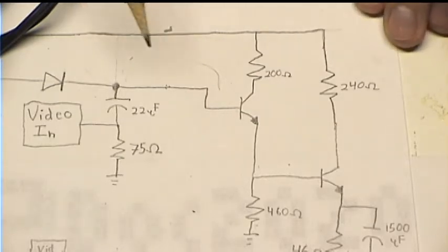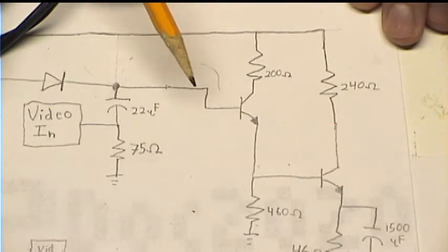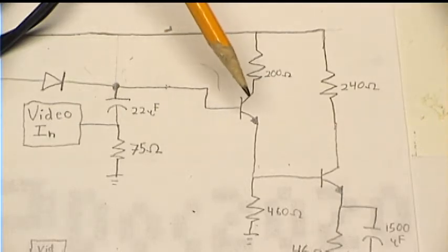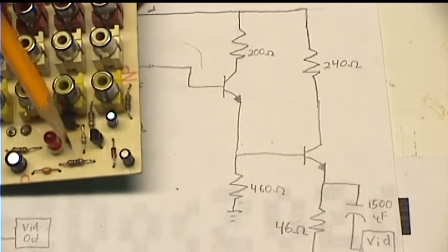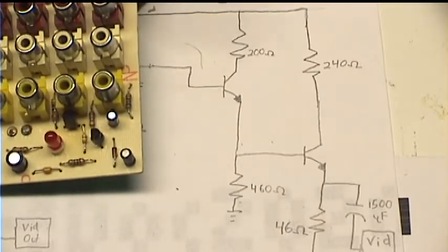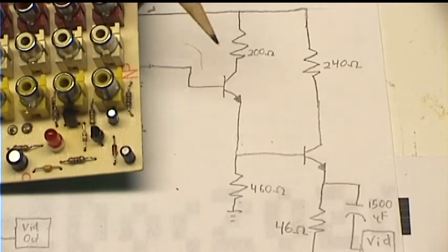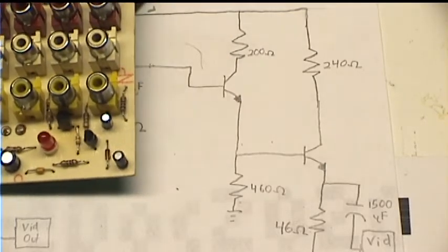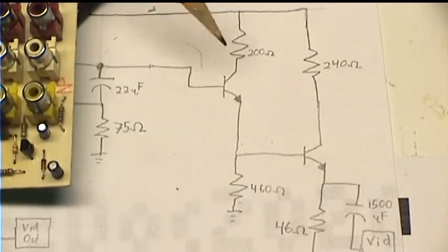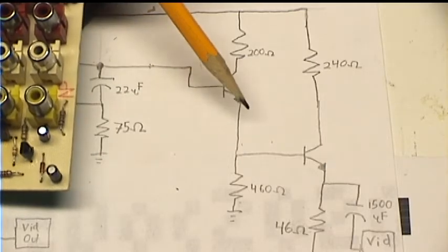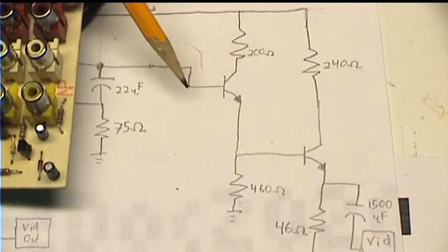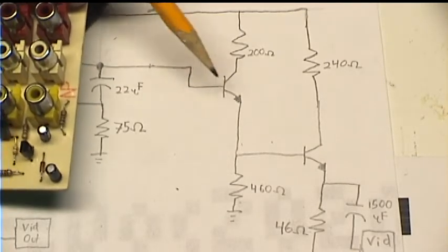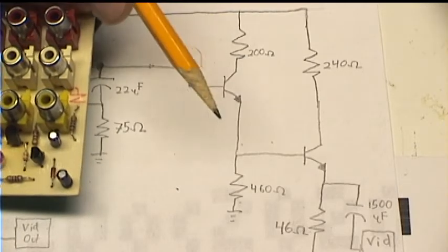Then once we have that elevated signal, it goes through this little transistor, which is this one on the board, in an emitter-follower configuration, which basically means the emitter is always about 0.6 volts below the base as it pushes current in to maintain that value.